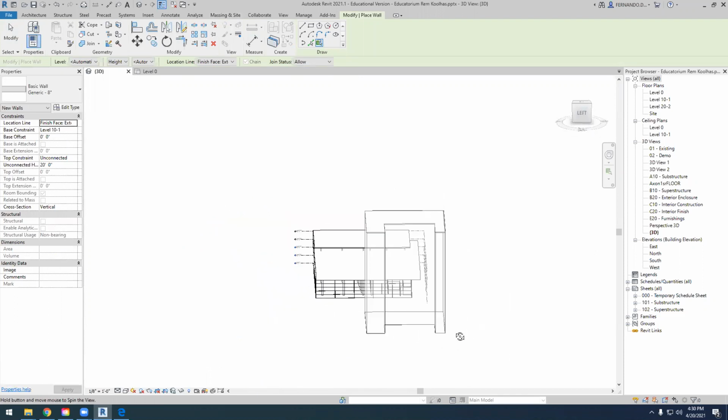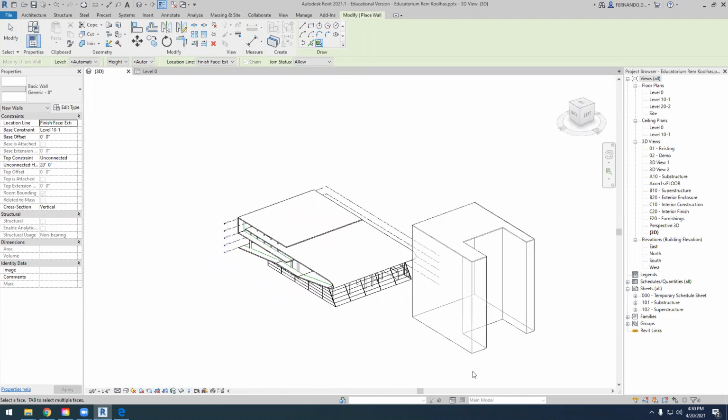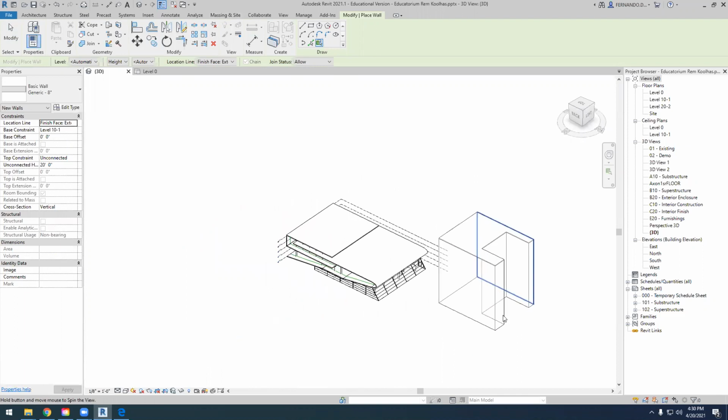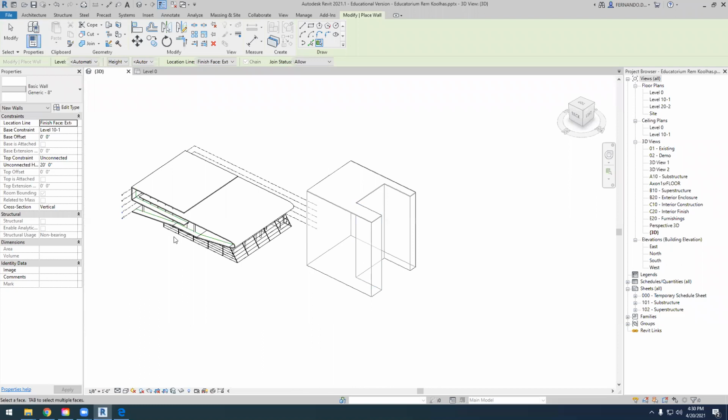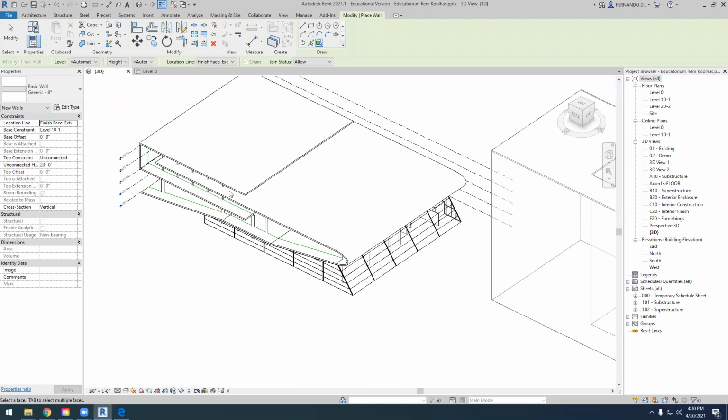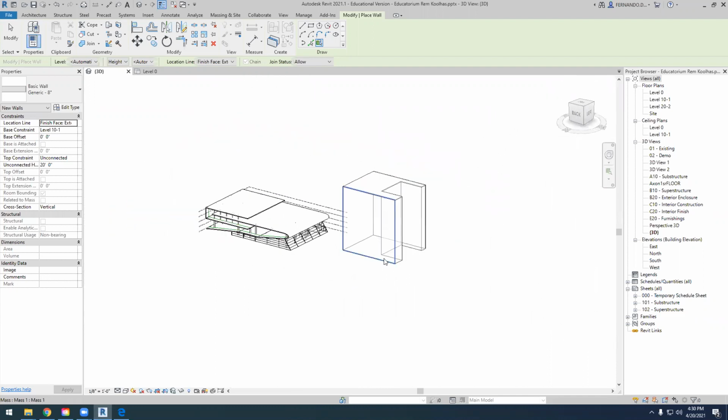Using massing inside, if we have complicated volumes, I can use this void form and subtract volumes. Can I do this with this kind of shape? I think we can. Yes, so let's do something more complicated with massing and modeling.